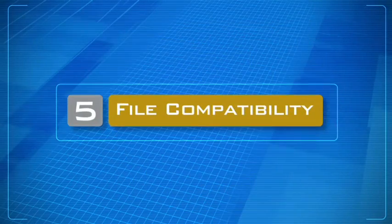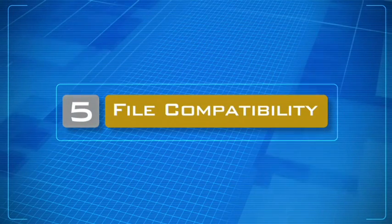Number 5, file compatibility. Civil 3D is based on the AutoCAD DWG file format. Backward compatibility with earlier versions of AutoCAD or Civil 3D programs may create issues when working in a collaborative environment. You will need to check if any third-party apps that you've come to rely on are compatible with the 64-bit operating system. Incompatibility can create serious workflow problems.